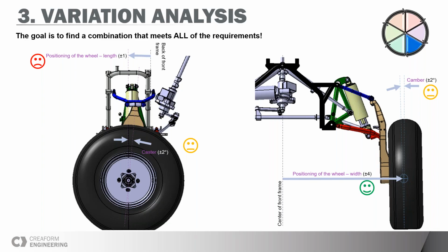And all of this while we ensure that we put tolerances that are still realistic in regard to the manufacturing process of each part. So at these steps, this is where we can identify a lot of flaws in the design that would have been only found later in the manufacturing process. But this is good. It will be a lot cheaper to correct them right now before the production is started than to debug everything during the production after all the tooling is made and the manufacturing method is defined.